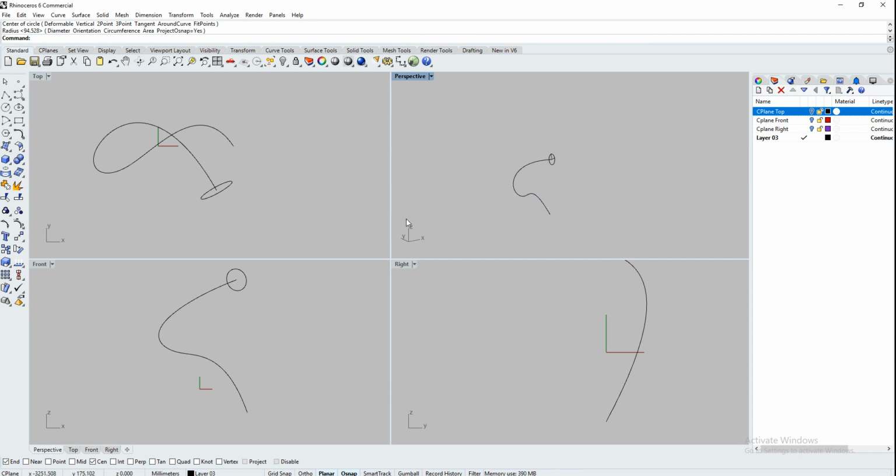If you're new to using Rhino, I wouldn't bother changing the CPlane. I would go ahead with the first approach, which is drawing on another plane and then repositioning the curve. The reason why is because you develop a really good skill, which is being able to reposition something within 3D space. And the more you practice repositioning things and moving them around, the better you get at it. So I've used orient perpendicular to curve and also move and rotate, but there's a lot more commands than that that allow you to reposition things.